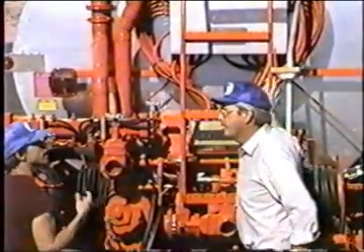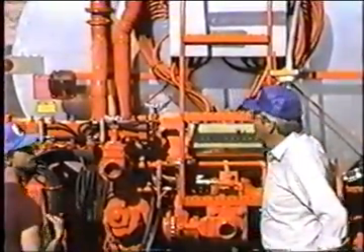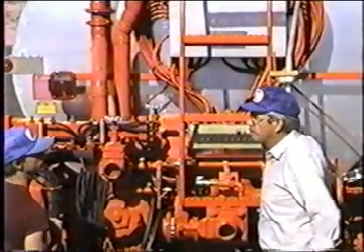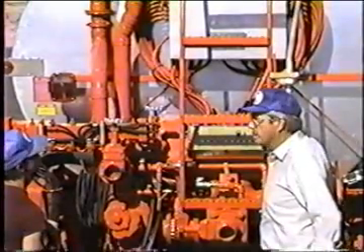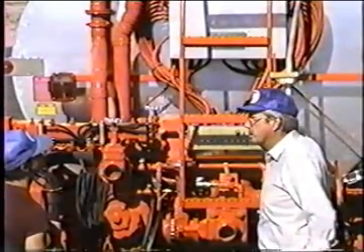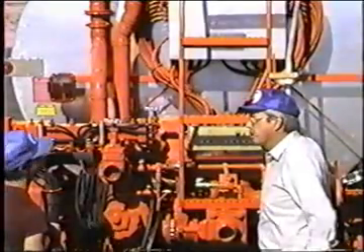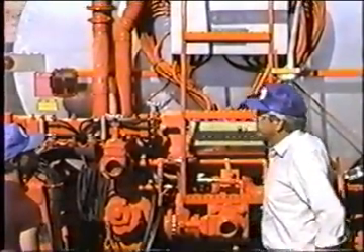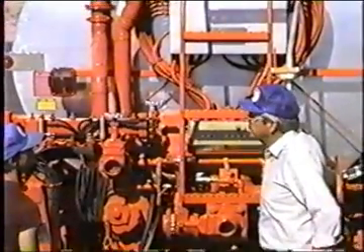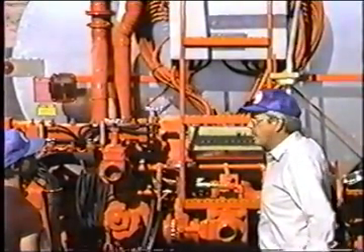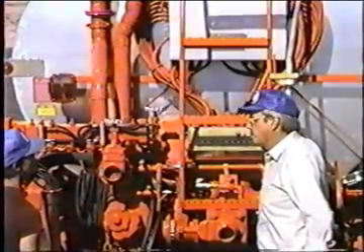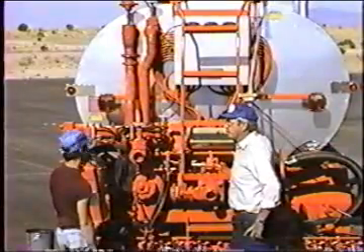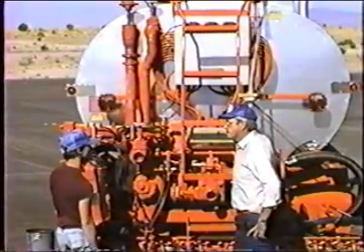Go ahead. How long does it take for the material to heat up? Normally, kind of a rule of thumb on a spreader like this is about 1 degree a minute. That is, every hour it'll raise the temperature in the tank about 60 degrees. 2 hours, raise it 120 degrees. The materials we're going to be working with are all different grades of asphalt road materials, and some are used at ambient temperature, some go clear up to 500 degrees Fahrenheit. All different grades are anywhere in between there, so we get into all different products and all different temperature ranges.